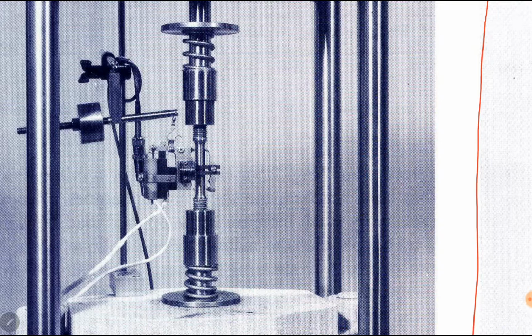So it means there is some permanent deformation in the material. If there is permanent deformation in the material, so this point C exists in the plastic region, and the material is behaving plastically in this region. So it is clear that if the material is coming back to its original position, original shape, after removal of the load, it behaves elastically, and otherwise it is behaving plastically. That point where this transition exists, it is called elastic limit or even yield limit.